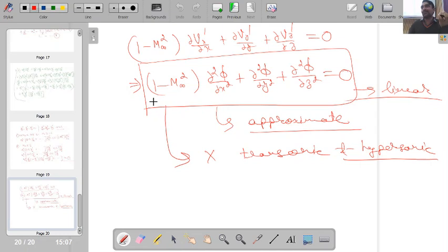And physically, if you see, in case of transonic flow, we find that our problem is strongly dependent upon the geometry, because transonic is nothing but the condition of transition. So near the condition of transition, if you make slight changes in the geometry of the flow problem, you will find your perturbations will be huge. There will be significant changes in the perturbation. So the physical nature of the flow is actually non-linear, which is mathematically creating a non-linear situation over here, particularly in that range of Mach number.